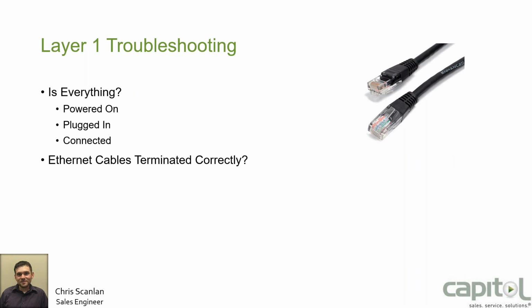Is it connected correctly? Is the cable terminated correctly? Just because your Cat5 tester tests out well, that may not mean those connections are good enough to actually pass a good data signal, okay? So, big one: terminated correctly, which can become a bad Ethernet cable.